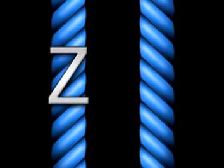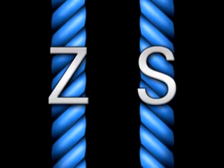The appearance of the twill line can be accentuated or diminished by the direction of yarn twist. Yarn twist direction corresponds to the angle the fibers are twisted to form the yarn. By looking at the fibers in the center of the yarn illustration, one can see that if the letter Z is superimposed on top of the yarn and the twist direction of the fibers matches the center of the letter Z, this yarn is said to have a Z-twist. If the letter S matches the direction of yarn twist, then the yarn is said to have an S-twist.